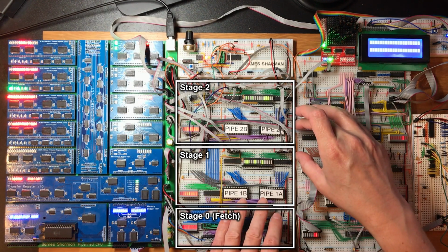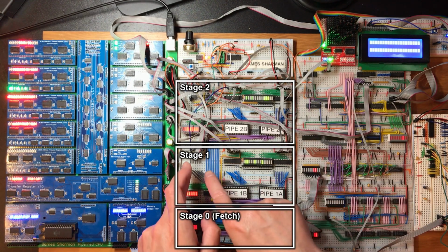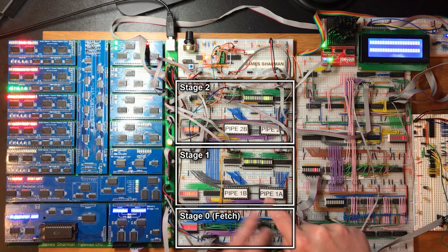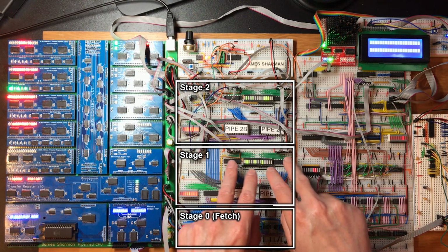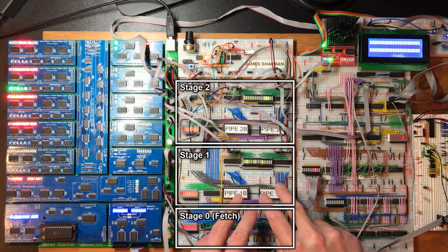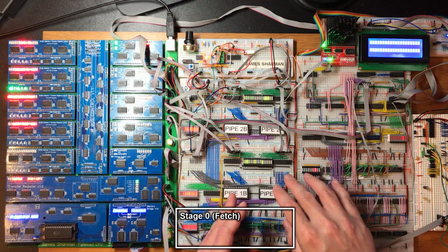These two pipeline stages are almost identical in terms of their underlying circuitry. They have the same main inputs, which are the flags coming out of the ALU and a couple of control lines. And then they each have 16 outputs that are going off to various other sections of the processor. Each of those outputs are different, so we'll need to redefine those.